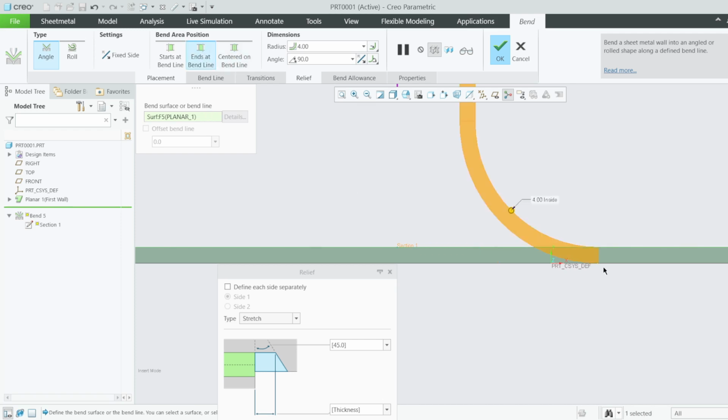You see, this is the point here. If you see now the center, it calculates the length, but now shifts by half the value, one value from this side and one value to the other side of the bed. Therefore, if you select centered here, you can see it is at the center. So the total length of this bed, half length shifts back, half length on this side. Therefore, for precision, I prefer using start at the line because I can easily control it.